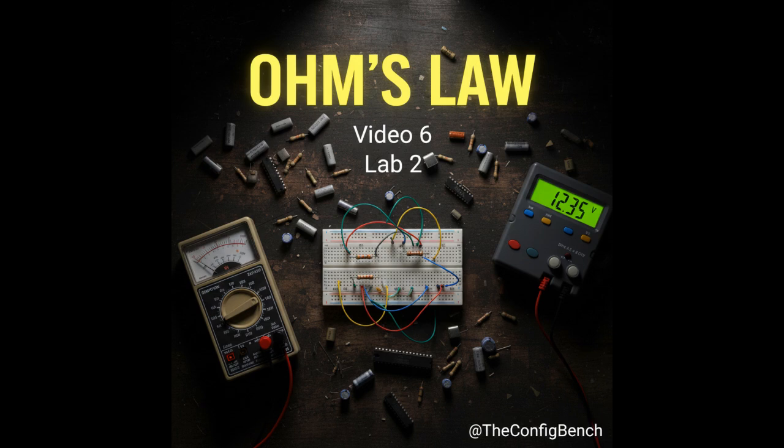This is John. In the last video, we took a single 47 ohm resistor, applied a 9 volt battery to it, and used Ohm's law to calculate the current before we even touched a meter. The math was right. Today, Lab 2, two resistors in series, end to end. When you put resistors in series, the resistance adds: 94 ohms total. Same 9 volt battery. We're going to calculate the current, then figure out how that voltage splits across each resistor. Then we'll put the meters on it and check our work. So let's do it.